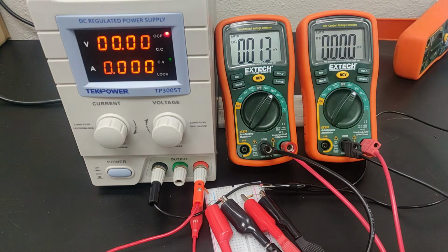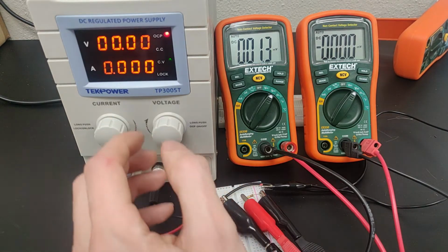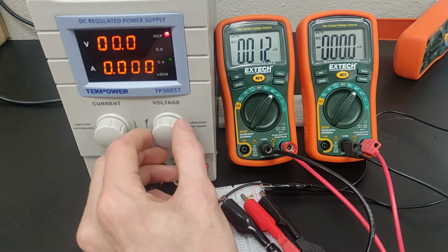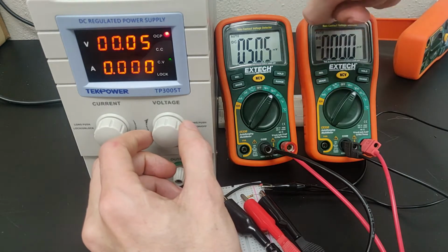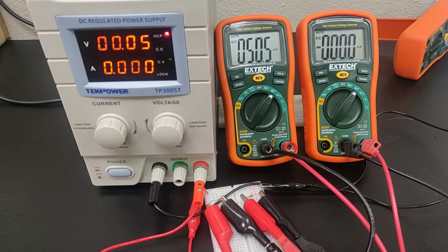Okay, we are getting some reading for a voltage over our diode, but I think in general we can just have our first point be at 0, 0, because I don't actually have anything being output to the power supply. So 0 volts for our voltage drop over our diode, 0 for the voltage across our resistor. So the plan is to increase our voltage from our power supply so that the voltage reading for the voltage across our diode is roughly in intervals of 50 millivolts or 0.05 volts.